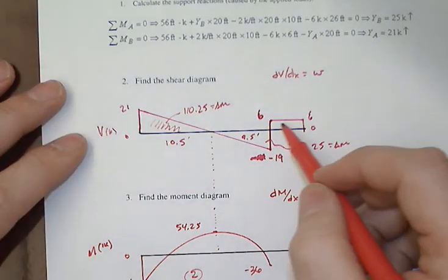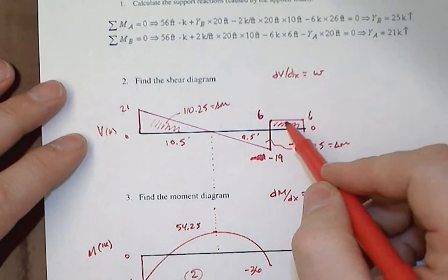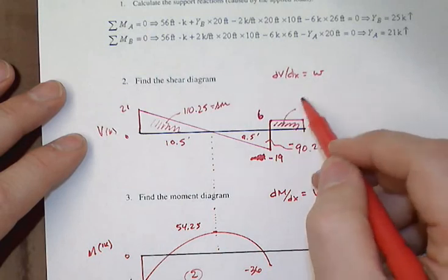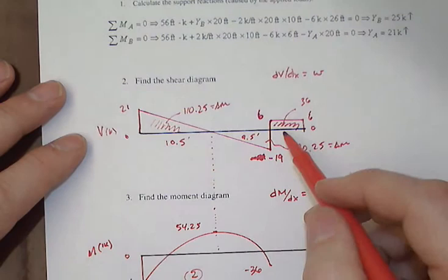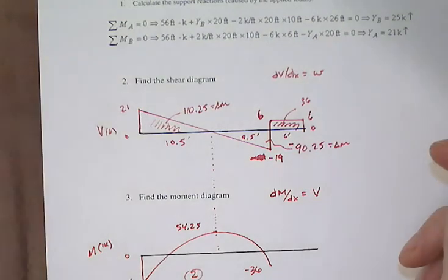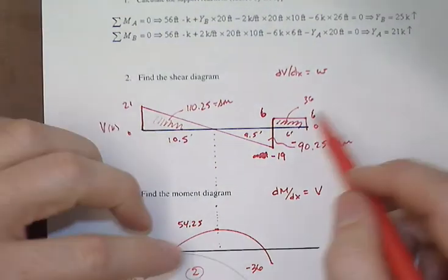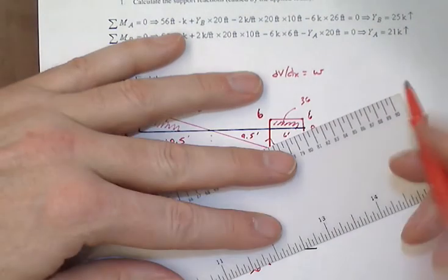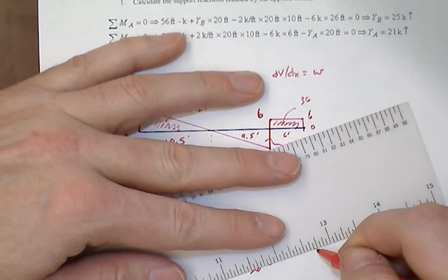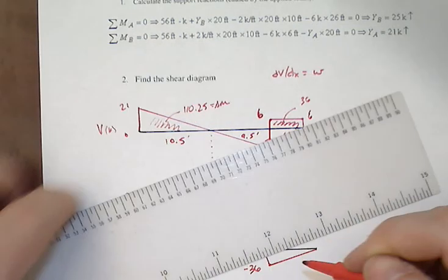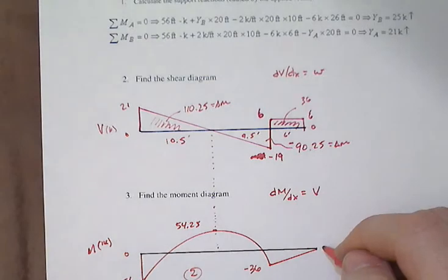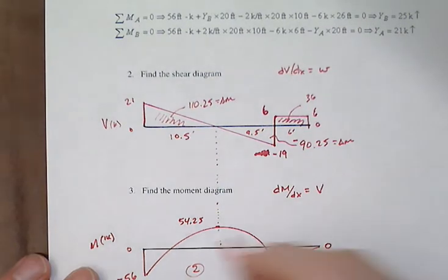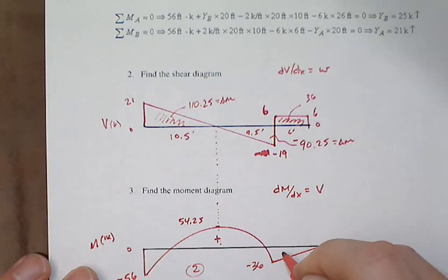And then notice that we've got to take care of the overhanging part. That area there is 6 times 6 or 36 because it's 6 foot long, and note that it has a constant slope, so therefore we're going to go up from minus 36 plus 36 gives us right to 0. That's good. It should close off, and straight line, and there's your moment diagram. So note we've got a region of positive moment, that's the smiley face part. We got a region of frowny face moment, that's the negative